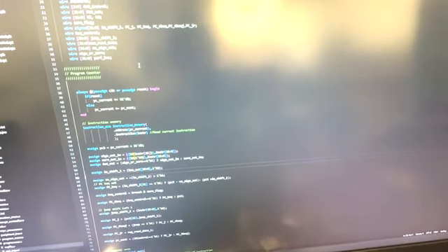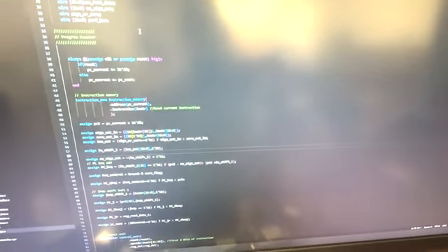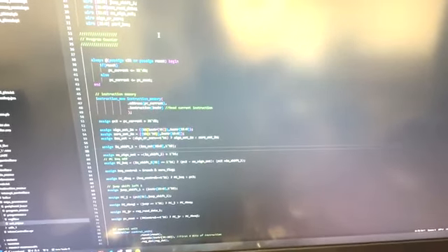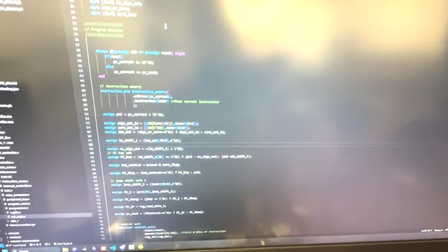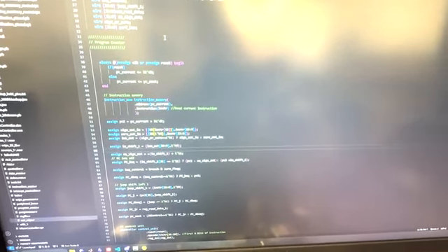This will increment every clock cycle, and when it reaches every multiple of 4, that's when it'll actually start the next instruction. Essentially, we're dividing our actual clock frequency by 4, but because some things take longer than others, we'll actually not increment by 1. I'll show you in a little bit. We then have our instruction memory that stores the actual code that we're running.